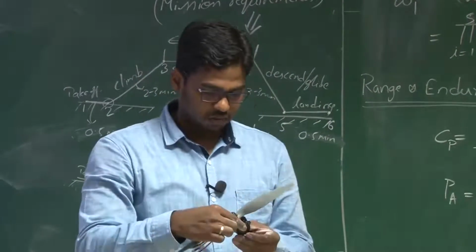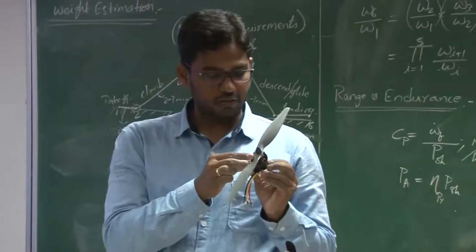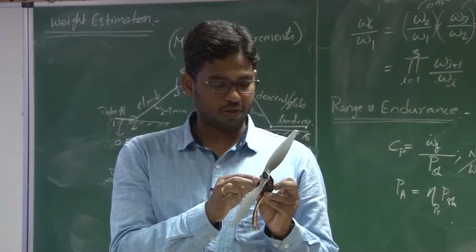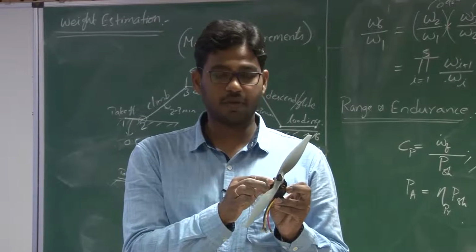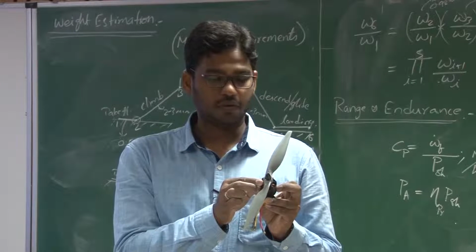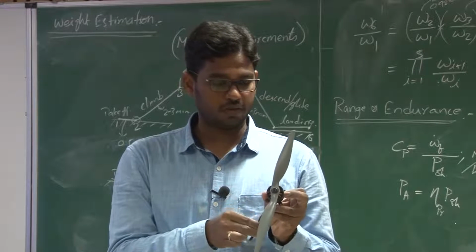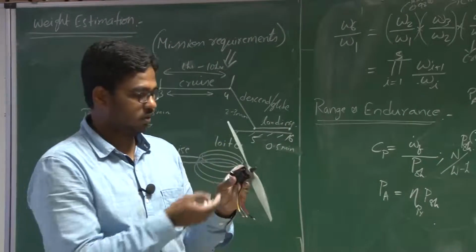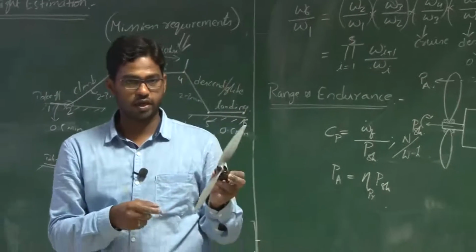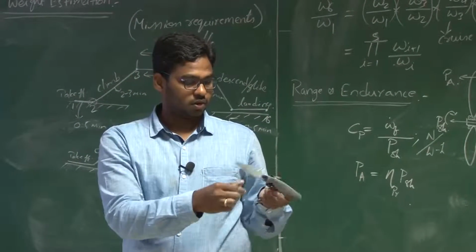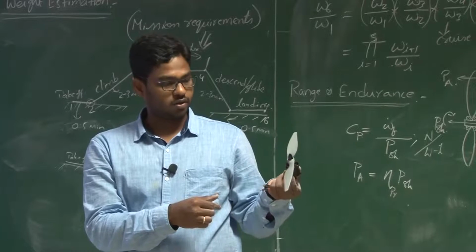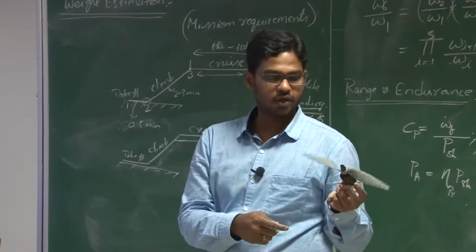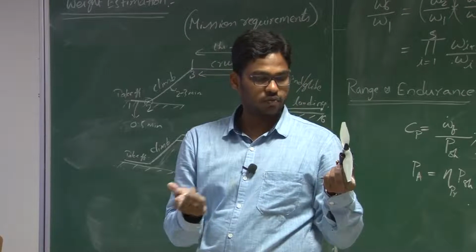This is typically a 1100 kV motor, which means it has an RPM of 1100 per volt, right? When you are operating this with a 4-cell battery, which is approximately 12 volts, you have to multiply by the corresponding RPM, and that's the maximum. It will deliver a thrust of 2 kgs when operated using a 12 volt battery.